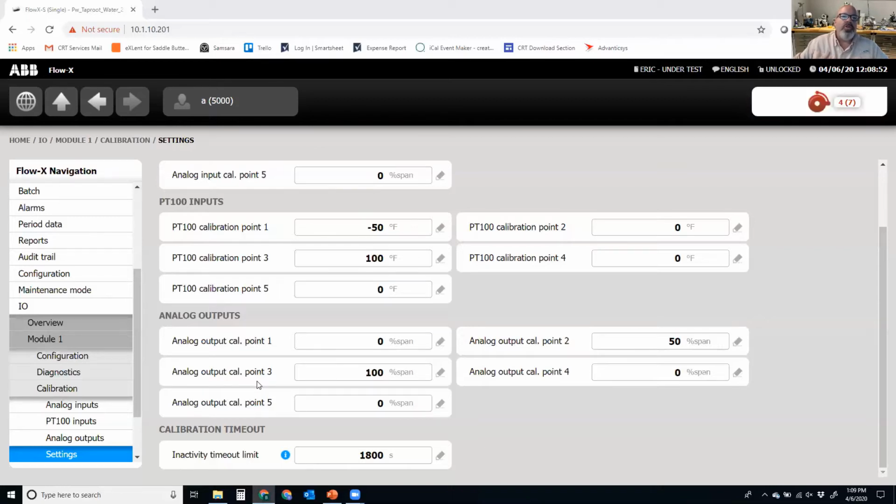As we're here, we're doing a calibration of the loop, or if you're actually doing it on a device that can do the whole process, the whole temperature range, and 5 points on that temperature range, then it's putting in a linearized offset, which is a very difficult word for me to say. But we're going to keep everything pretty simple here, and we're going to do a 5-point calibration curve on an analog input.